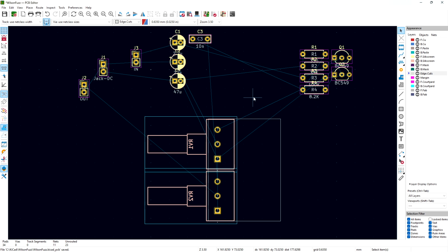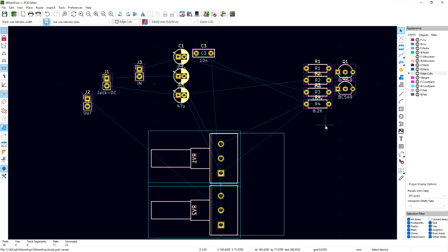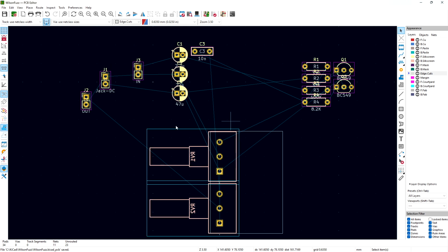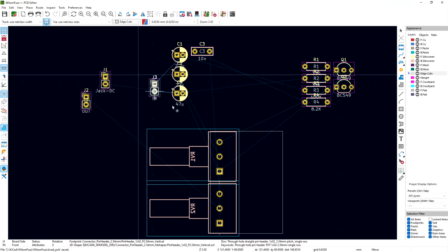In some cases, it is a bit cheaper if we are not going to do anything here with any components. We could put components here as well if we can fit them, but we need to be careful about what we're doing. We need to be careful about the size of components, width, etc. So it's a bit tricky. Ideally, we won't put anything here, okay? And I still haven't started routing this. This is getting a bit out of control. Yeah, I'm out of control.